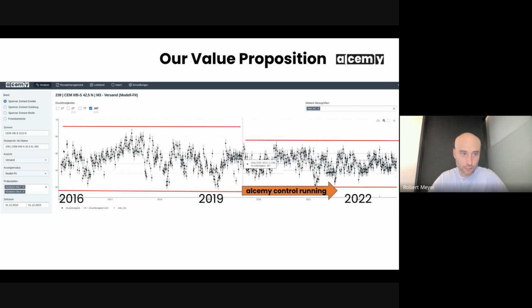So you can see here a lot of fluctuations in cement strength. Each black dot here really corresponds to one of these measures where these concrete cubes were formed and then crushed. And then we applied our algorithm, and we can see that we basically reduce these fluctuations by 30%-ish. And this already can help. This improvement of the standard deviation of the strength measurements of like 20-30% can already mean like $500,000 in savings.